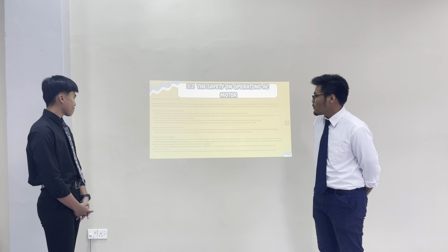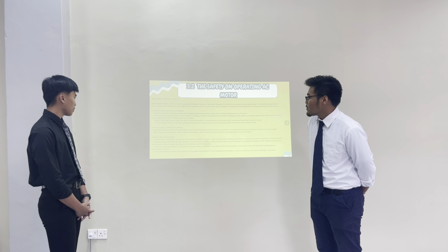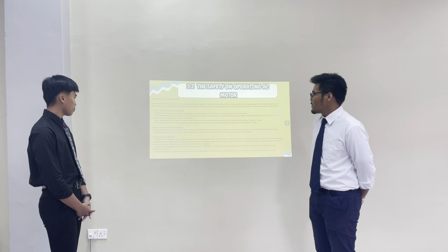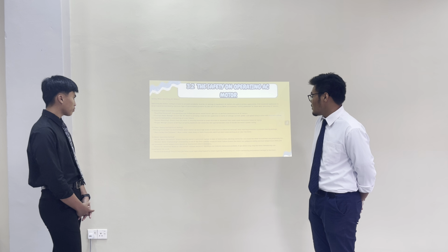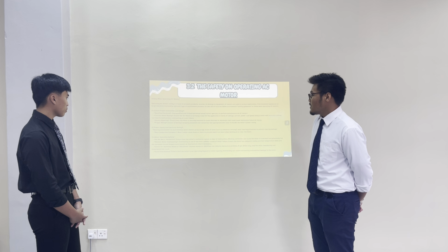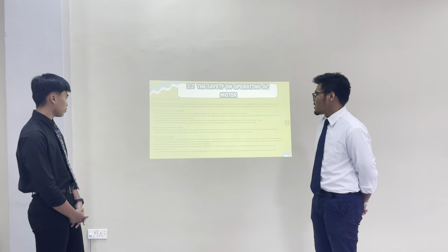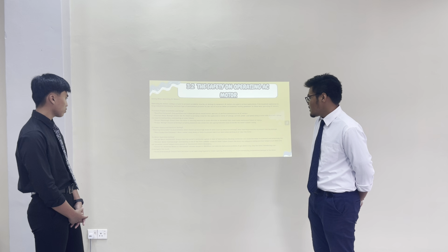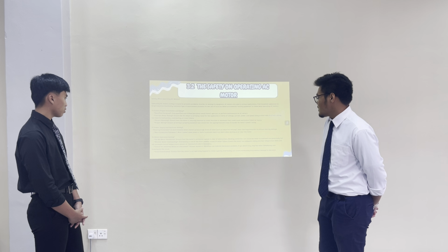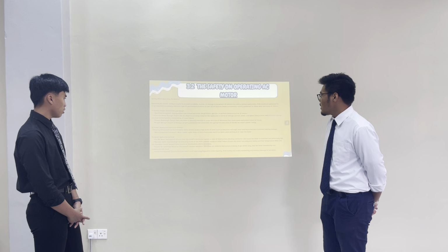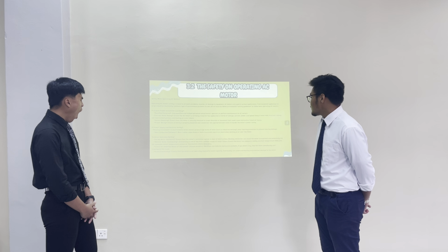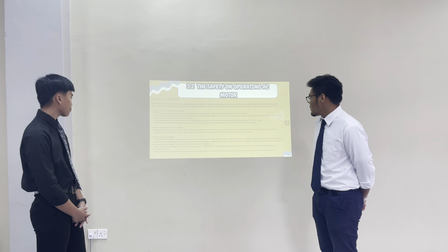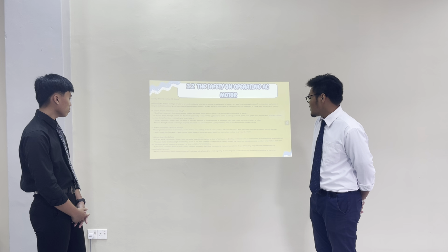First, ensure proper installation and setup. Qualified personnel: only qualified and trained personnel should install, operate, or perform maintenance on AC motors. Correct motor ratings: ensure the AC motor is correctly rated for the application in terms of voltage, current, power, and speed. Using a motor with incorrect ratings can lead to malfunction, overheating, or even failure.